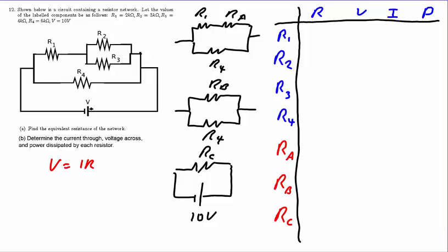First, let's fill in the given set. Here we've chosen to express the resistors in ohms. You could also do this problem by expressing the resistors in kiloohms. We recognize that RA is made out of the parallel combination of R2 and R3. R2 is 3 kiloohm and R3 is 4 kiloohm. If we put 2 3 kiloohm resistors in parallel, then we would get 1.5 as our answer. If we put 2 4 kiloohm resistors in parallel, we'd get 2 as our answer.